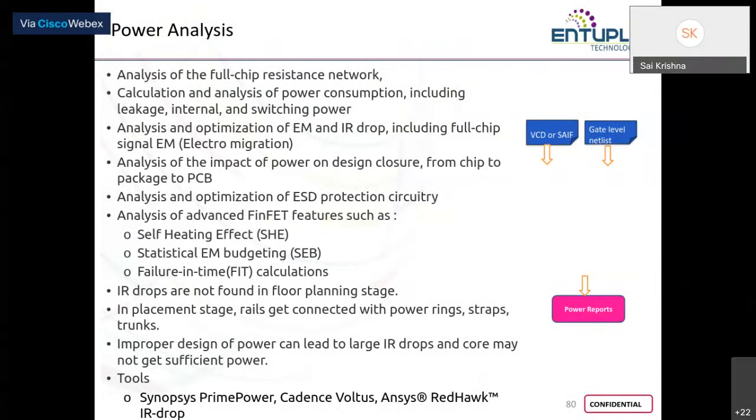So once your timing is done, you also need to check for your power. Generally, in synthesis, you have only seen the numbers for power in your report, or even in your physical design, you only check for the numbers. But power analysis is a completely different branch which looks into far more fascinating concepts than just what is power dissipated.